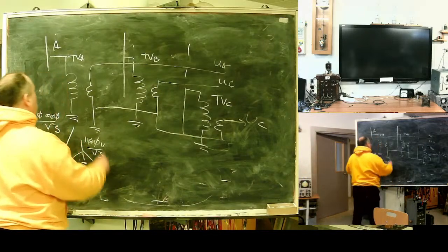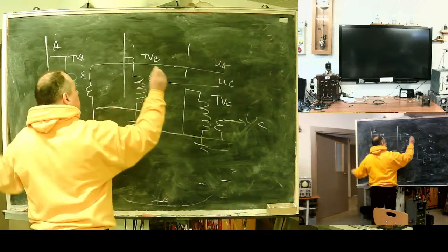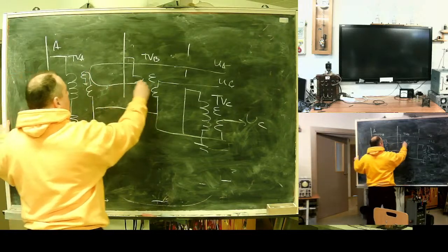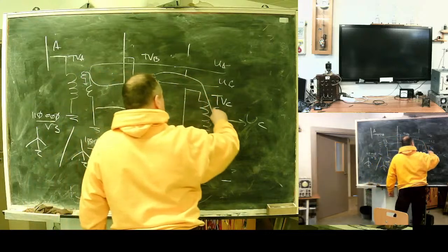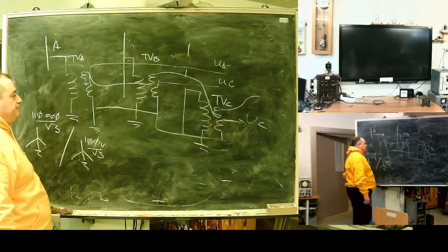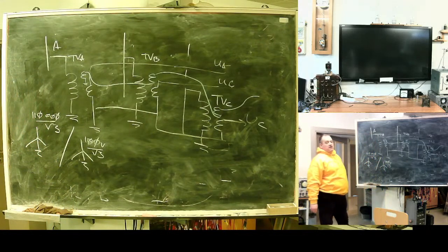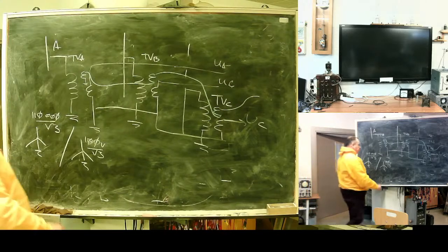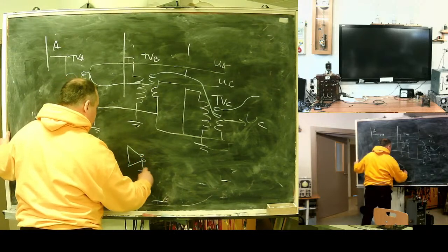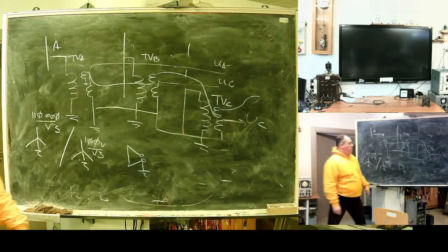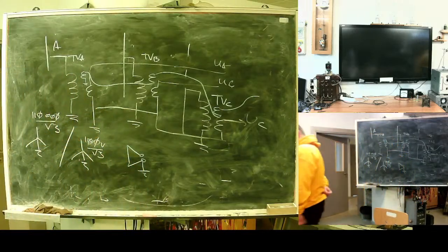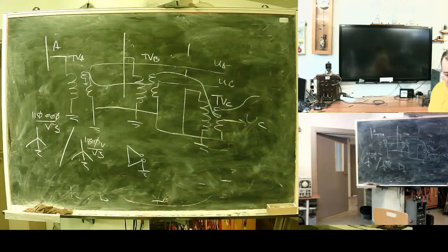Also, these transformers, it's an industrial standard, are equipped with a supplementary set of windings. What will I get from this? Open delta. What is here? Sum of A, B, and C voltage.